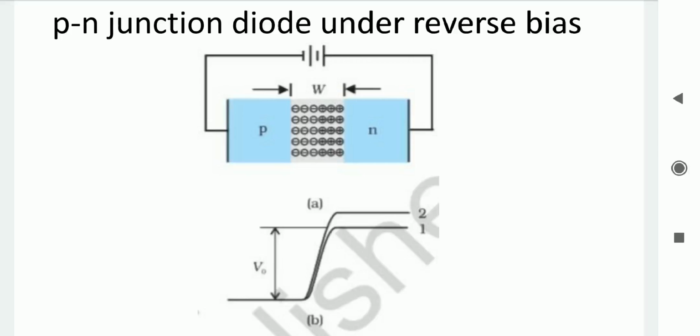This diode in the reverse condition is not dependent on applied voltage, because as the voltage becomes very high, the voltage drop across the junction will increase, but its current variation is not available. So here a very small voltage is also enough to widen the depletion region, and accordingly the minority carriers can get energized and generate the current.